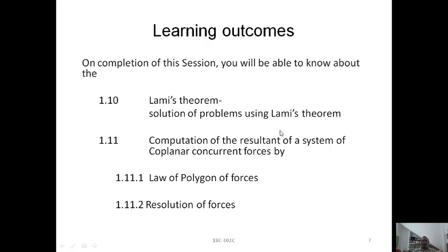Lami's theorem is intended for three forces, among which if one or two are unknown, you can find them using Lami's theorem. Earlier, in the triangular law and parallelogram law of forces, we dealt with only two forces, whereas in Lami's theorem we will deal with three forces. In the law of polygon of forces, we deal with n number of forces.